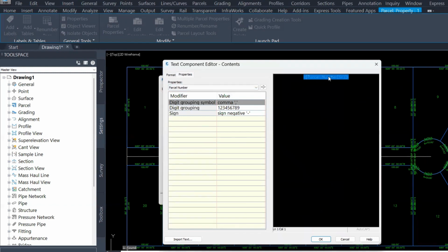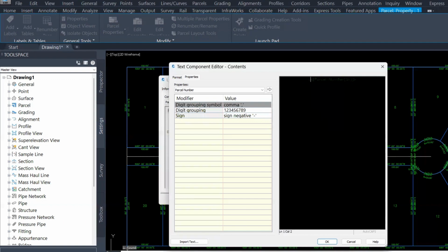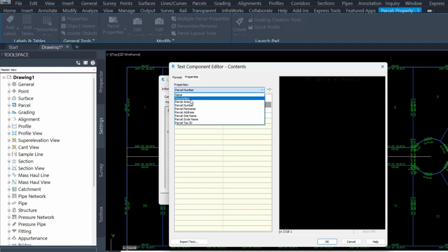In this case, parcel number is added in. So for example, we have parcel numbers and it just displays a number, but let's say we want to describe it as lots. So you go ahead and type in lots for that, and then the parcel number, which would just indicate a general display of the label for all the parcels or lots you want to show. Click enter right here. It gives you different properties options, like the name of it, if you set out a name.